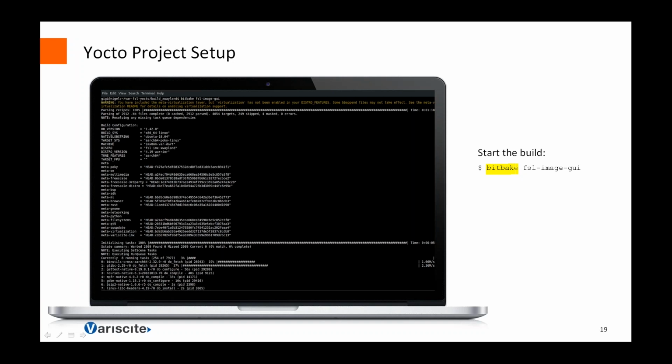It's the command that activates the build process. Here we provide as an example the build of the fsl-image-gui, but you can also build a specific package only, for whatever you want to do. There are several options with bitbake, including tracing the environment variables that are used during the build without actually doing the build. It's a kind of dry run.